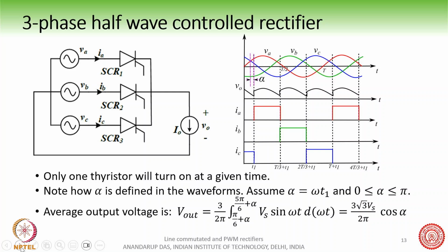So what we will do here, now we have these three-phase waveforms which we have plotted here, and we can give these the names SCR 1, 2 and 3. So when do you think the SCRs will conduct? For example, SCR 1 will conduct whenever the voltage VA, out of the three voltages VA, VB, VC, is the maximum of the three. That is the point where SCR 1 has the natural point of starting, and this natural point of starting is obtained here.